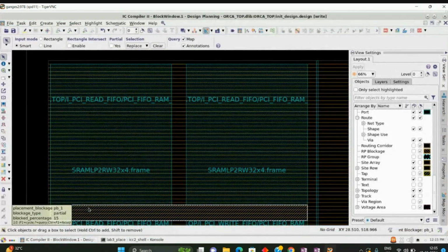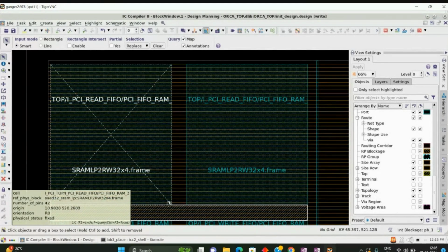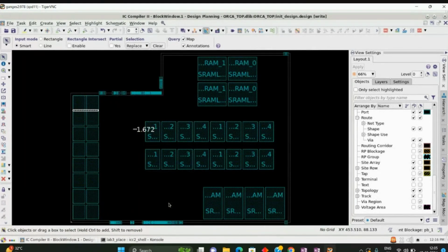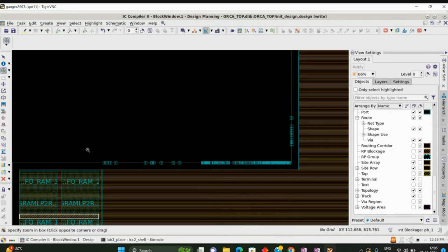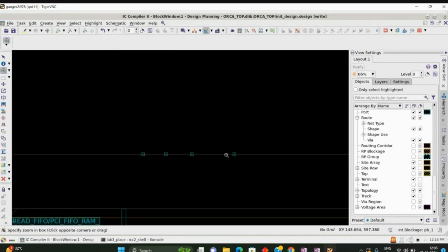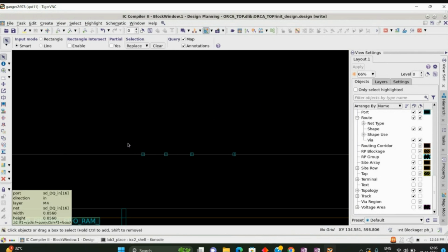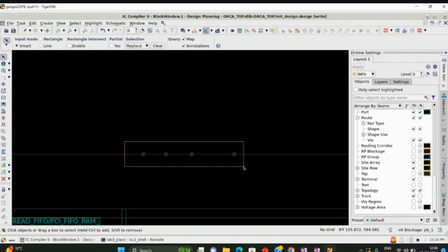Okay, so if you want some area, suppose you want to keep in some locations, so how will we do the port placement and all, no? So like this we will apply the port placement also actually. So here in this area some 4 ports are there, right? What I'll do, I'll just take this partial placement blockage and I will apply to this area.